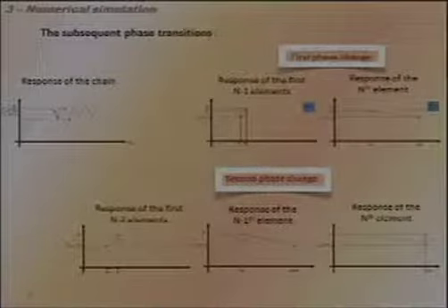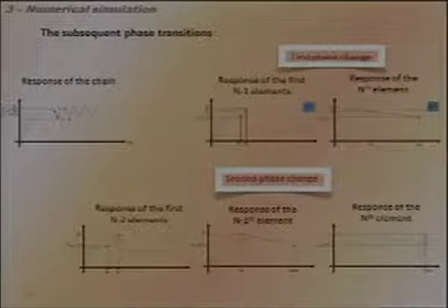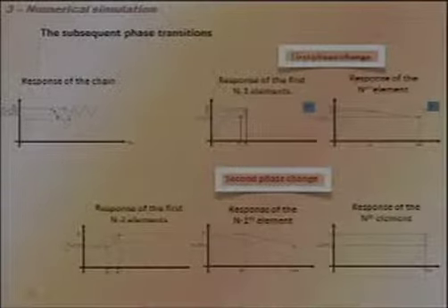Just some comments about the role of viscosity. We have to note that the determinant of H is not 0 at the point where the derivative is 0, as it would be if we were in elasticity, but there is a delay because of the viscosity. And that's just to understand what happens. There is one spring going directly to the second branch, and we have to compute the equilibrium resulting from that after that jump.